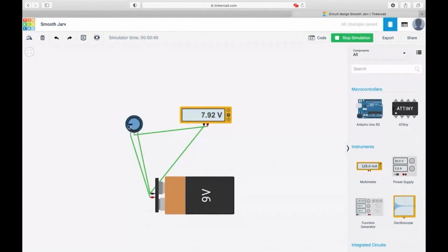As I move away from this end, R1 is increasing, and the displacement of the wiper is decreasing the voltage. And if I move it to the extreme end, that means R1 is maximum. In that case, the output voltage will be 0. This is just to give you an idea about the potentiometer.